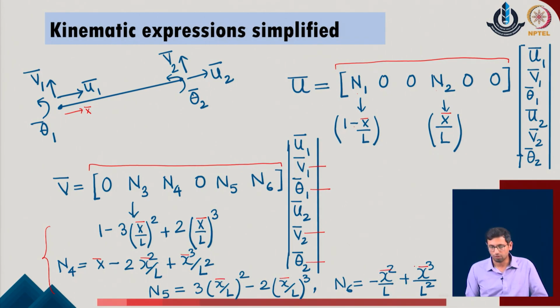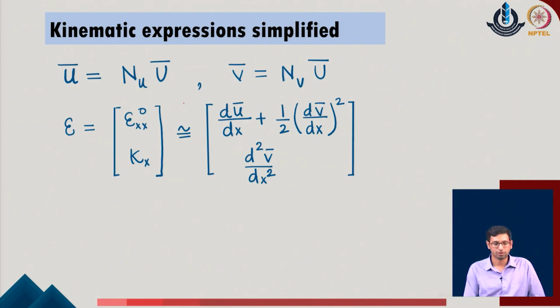Now, once we have identified these function fields, we consider that the standard equation which we earlier described for the strain parameters can now be converted using these shape functions of the given system. There is a reason to call them shape functions also, because if you try to draw the distribution of them between the two nodes of the given system, the function varies as 1 minus x bar upon L.